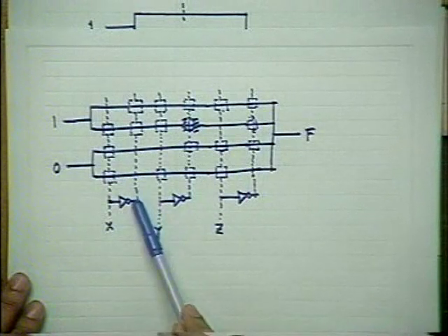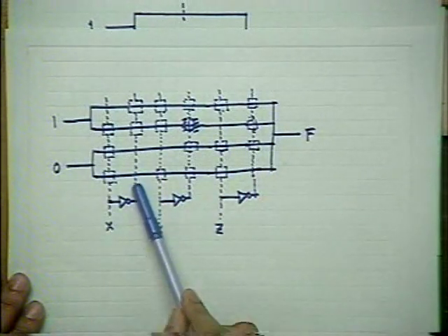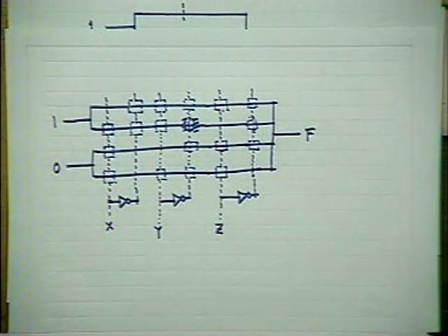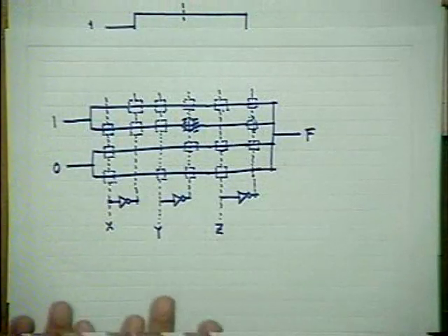Okay? So you see that all your input signal is being applied at one end, and the signal is being transmitted by poly line. For the diffusion line, there is no problem because the diffusion line is very near. The RC delay will not be that much. But what about the last line on the other end of the chip? Because polysilicon, after all, has much higher resistivity. The polysilicon gate which is used for MOS realization is heavily doped, N+ usually. But its sheet resistance is usually quite large compared to metal sheet resistance. Suppose I had used a metal gate, the sheet resistance would have been very little. So RC delay for a metal gate would be very small. But one level is normally used as poly level, because we have to use at least two to three levels of metallization. So one level is always poly level. Please remember. So what is the problem here?